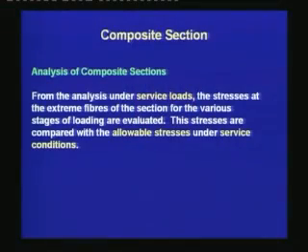From the analysis under service loads, the stresses at the extreme fibers of the section for the various stages of loading are evaluated. These stresses are compared with the allowable stresses under service conditions. That means, once we find out the stresses at the extreme edges in the concrete, then we compare them with the allowable stresses given in the code and make sure that these stresses are within the allowable values.